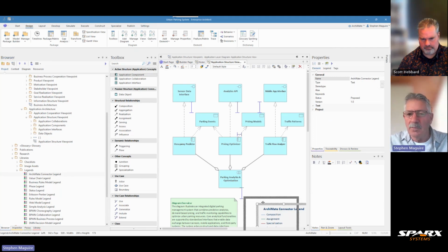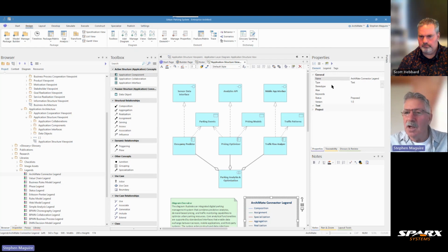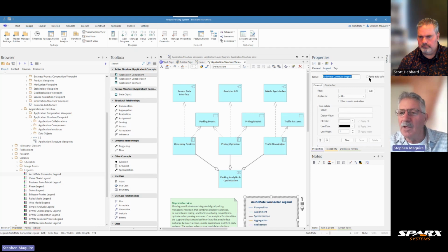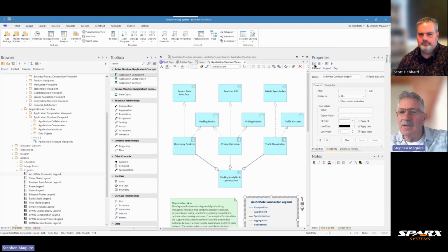And you can see here that the legend, let me just check whether the legend's been applied there. Apply the auto color. So if the legend doesn't, for some reason, come on, it's because that apply auto color has been turned off. So let's turn that on again and save that legend. And now you can see that the colors have been updated.